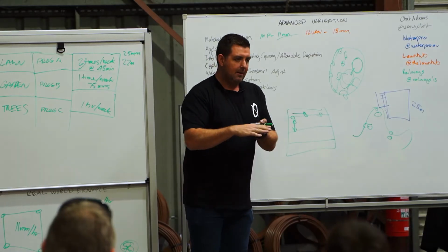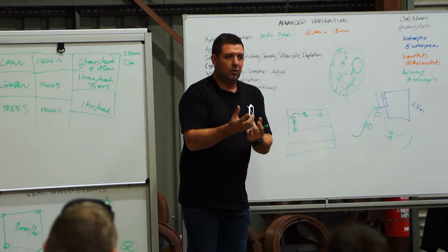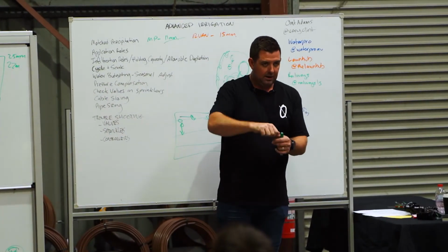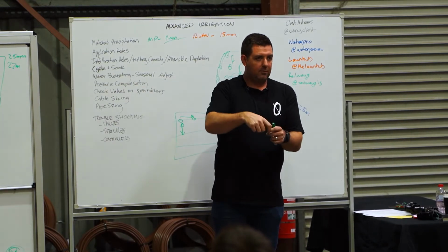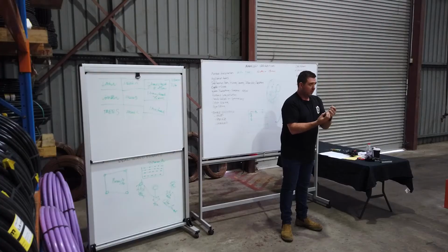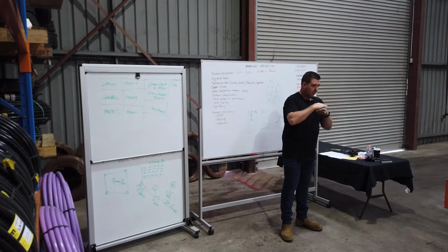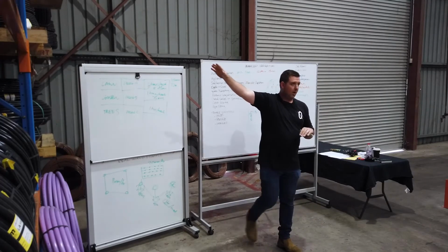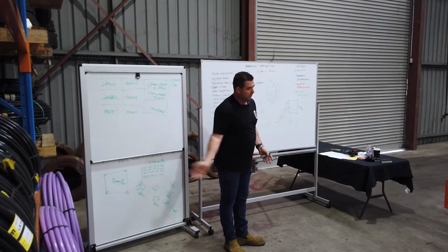It's basically, it pushes into the filter. So if you bought a Hunter Pro spray, which you guys would have all used, they're the ones that have got the grey nozzle that snaps off, that has the flushing nozzle. You screw that out, you stick this rubber into the filter. It sits a bit more proud than it would have traditionally, but when it closes, the rubber seals off the bottom of that sprinkler, so all the water that's sitting above it stays in the pipe. So next time you turn it on, it's pre-charged and off it goes.